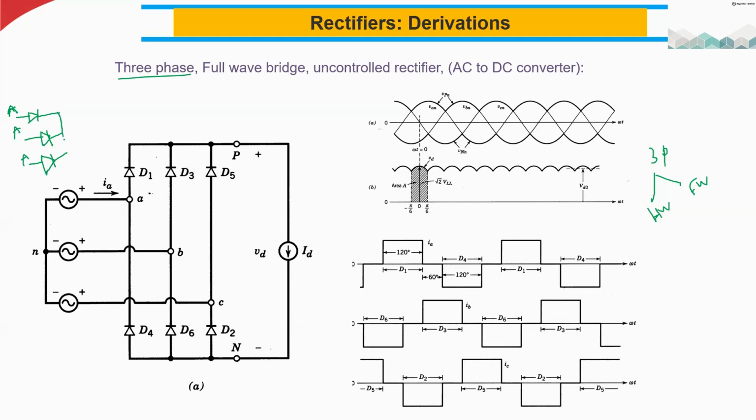So now I connect all the cathodes together. And then I connect the load here. This is the ground. This is the resistive load. This is D1, D2, D3. Maybe here I apply plus 5 volt, and here I apply 3 volt, and here I apply 1 volt. You see here, I am applying plus and minus. All three diodes are forward biased, and all the cathodes are connected together, and I have the load.